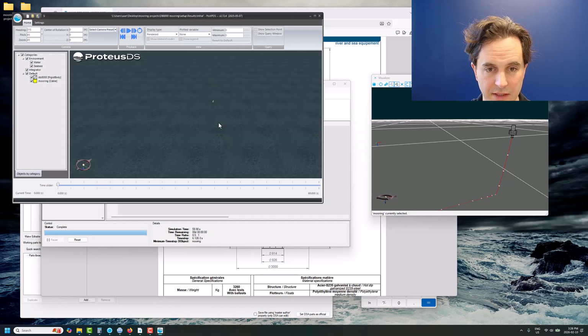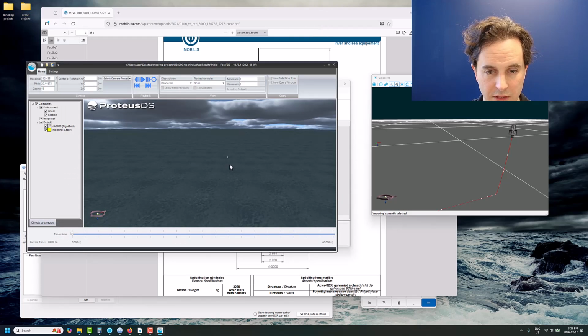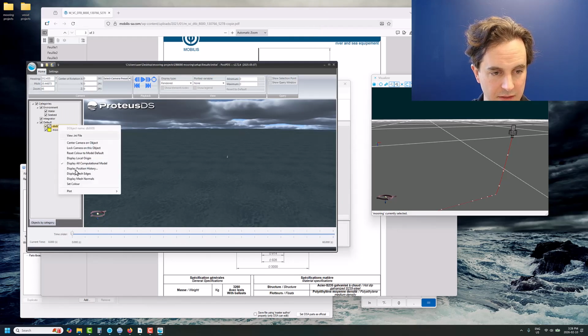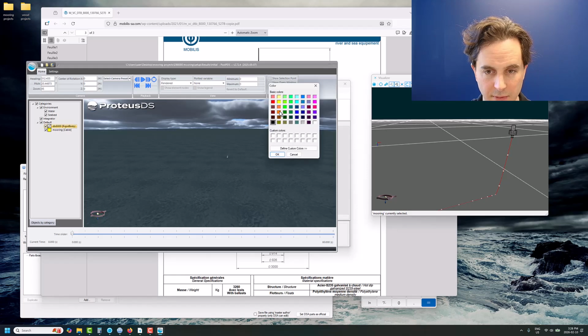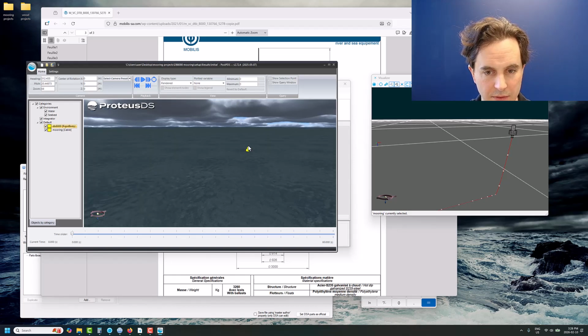And you can see here's our little 3D kind of view of the ocean. The buoy's a little kind of default gray color. Maybe we might want to right click on that, DB8000, set it to be nice bright yellow color. So the buoy's got to settle a little bit. Remember we turned waves on to ramp up over 10 seconds, so it'll take a little bit of time for the waves to start showing.